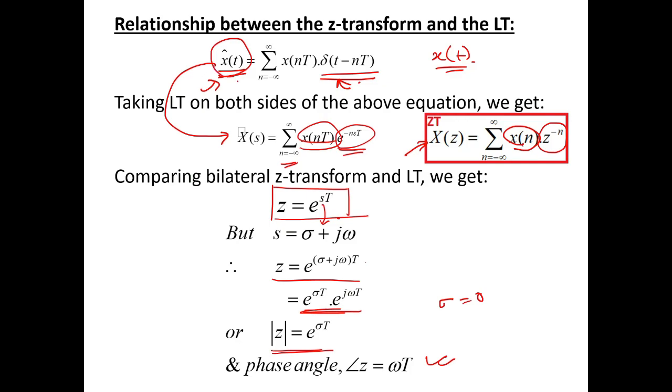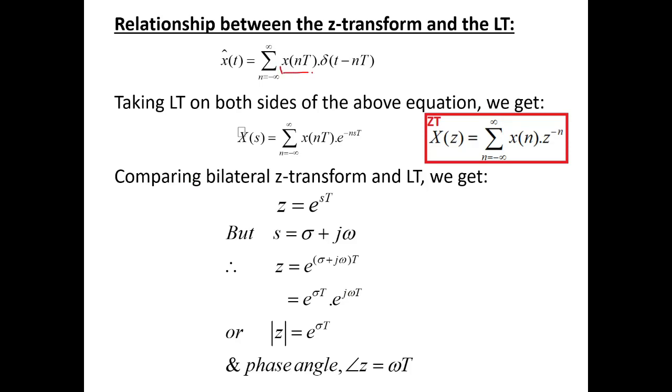If you see, when I said I have sampled the signal, in the constituent signals, there are two signal components. One is the original signal and the other one is the impulse train. The impulse train has its own frequency, right? The frequency of the impulse train is called the sampling frequency. It is regarded as sampling frequency and it is given by Fs.